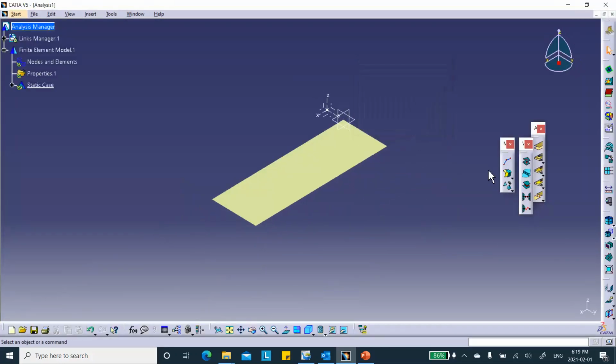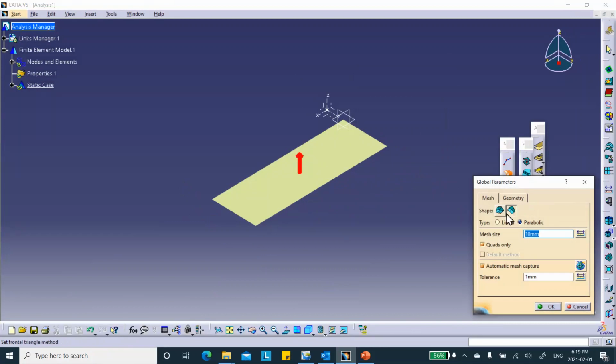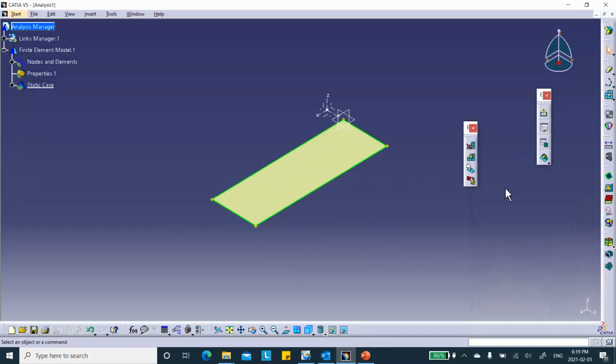And I'm going to mesh this thing with a surface mesher where I have the ability to create nice quad type elements, parabolic quad type elements. Ten millimeters, so there'll be 30 this way, and no, wait a minute, if this was 30 this way and 10 in the width direction, and mesh it, or zap it as I call it. There we are. Okay, so this is done.